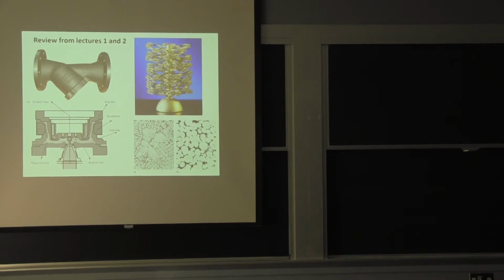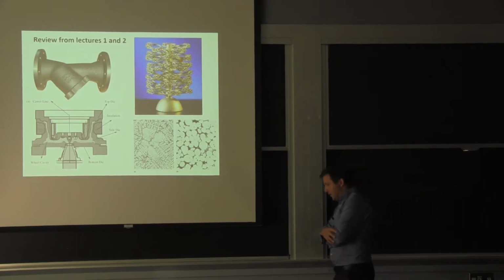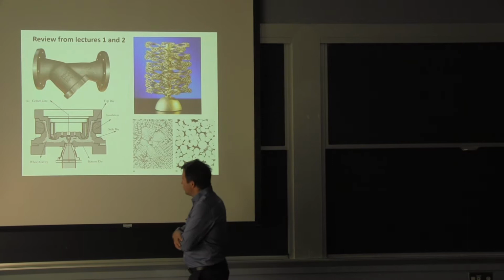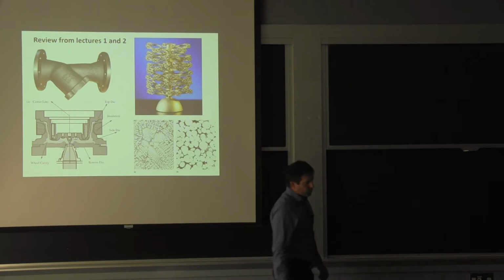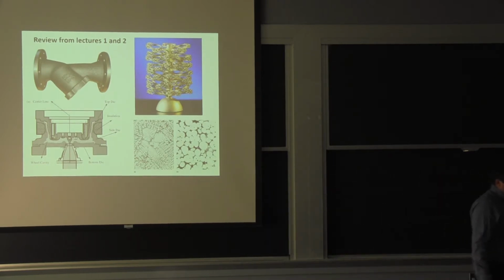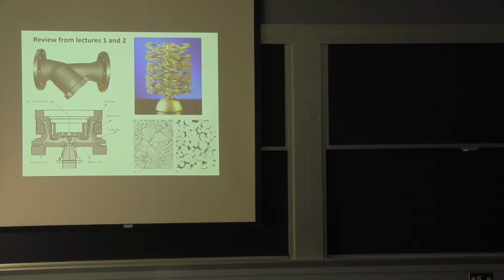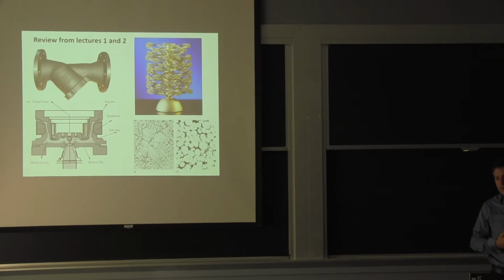We talked about die casting for aluminum wheels. That's the lower left. And I think I emphasized enough that one advantage there is you get a bigger cooling rate because you get the metallic molds as opposed to ceramic or refractory molds or sand molds. The other aspect is that it's under pressure. So what we were talking about, the little experiment with the heat transfer with the mold, if you keep applying a pressure, you help maintain a good heat transfer coefficient. And you also make more sure that it's going to be homogeneous through the wall.